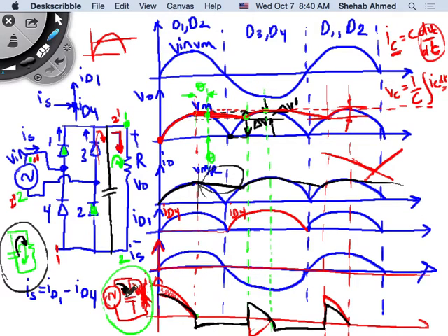The equivalent circuit looks like this: a source with an RC circuit across it. Then what I will do is charge the capacitor. So during this period where I'm charging the capacitor, supply current will come from my supply and charge my capacitor. So my red waveform is like this.